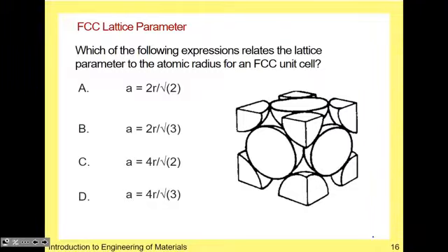So we discussed before how to relate the lattice parameter, or the lattice length a in a cubic system, particularly FCC, to the radius of the atom. For all these systems, you just need to see where the radii of the atoms touch each other, where you have a continuous length and there aren't any gaps.